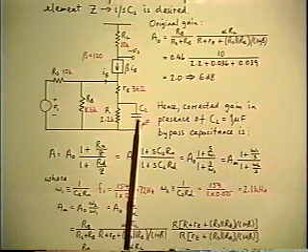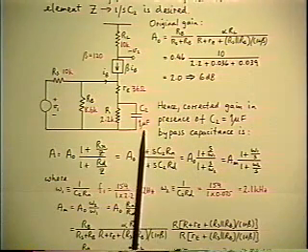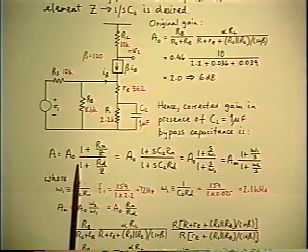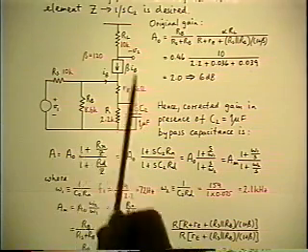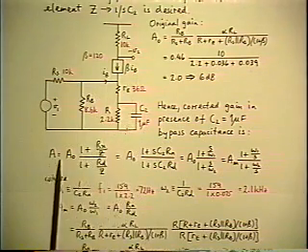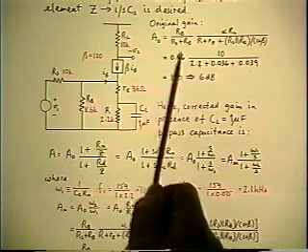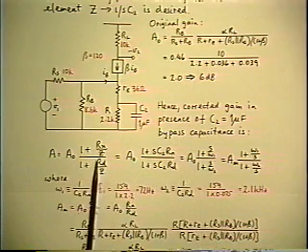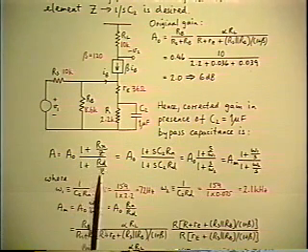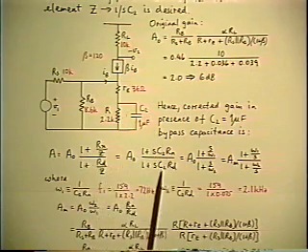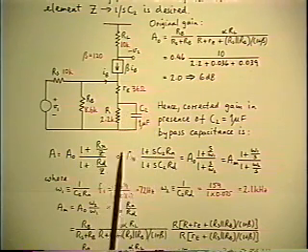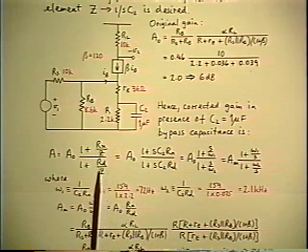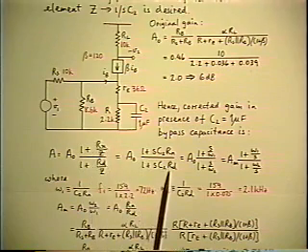So the extra element is a capacitor. And all that's left to do is to substitute into the theorem. The gain of the stage in the presence of the C2 is the gain that we had to begin with, which is the original reference gain modified by the correction factor that involves the element that we're putting in, which is Z, and Z is 1 over SC2, and the two driving point impedances. In this case, RD and RN.